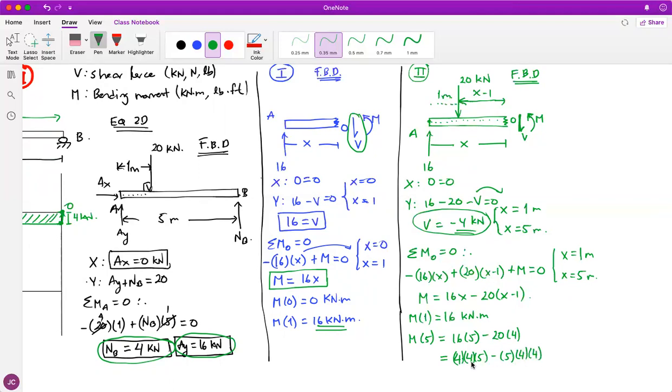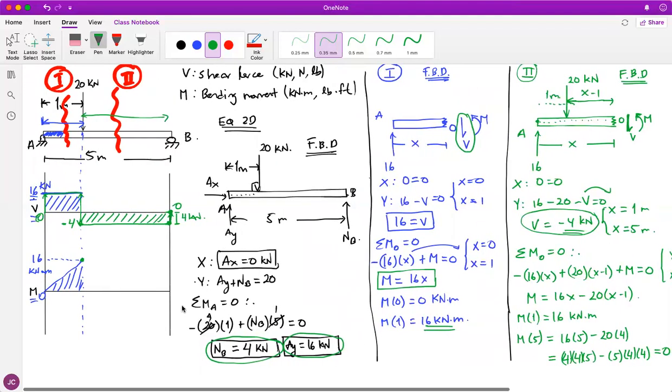So maybe you see now that this guy is actually the same one here and the same one, but with a minus sign. Therefore, this thing equals 0. So those are good news. That you get to a 0 at the end of the beam is good news because you got to equilibrium. Now, it means that you started at 16, sorry, not 6, but 16 for the moment, and you ended at 0 for the moment.